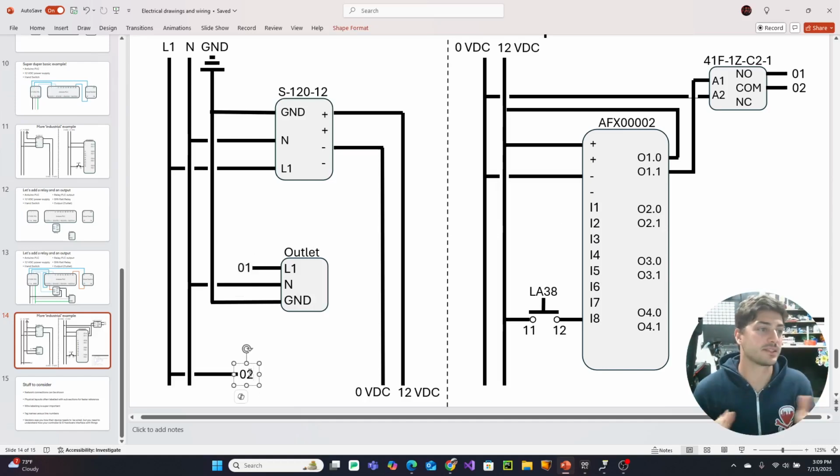And this is a massive simplification from how a large control panel would do it, but it's not always feasible to show every physical connection in your drawing in one nice, clean, continuous view. And if you look at the relay, which we've added to the top right, you can see output channel 1, wire 0 and wire 1 are pulling in the A1, A2 coil side of the relay, just like we saw before.